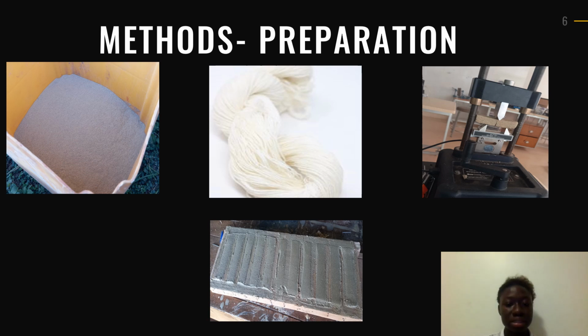And after they were casted, they were left indoors for 24 hours to avoid cracking when exposed immediately to the sun. And after, the samples were left in the sun for 1 week to dry completely. Then the samples were taken to the MEC lab so that compressive testing will be done on the cylindrical samples, whilst 3-point bending test will be conducted on the rectangular samples. So the fibers were oriented randomly. That means it will be stronger in either direction, whether longitudinal or transverse direction.